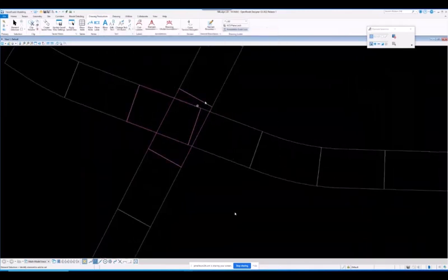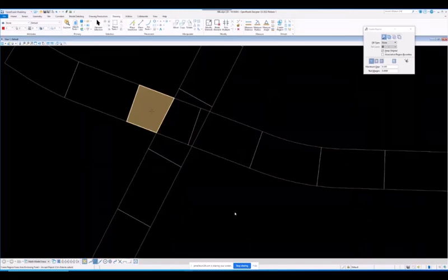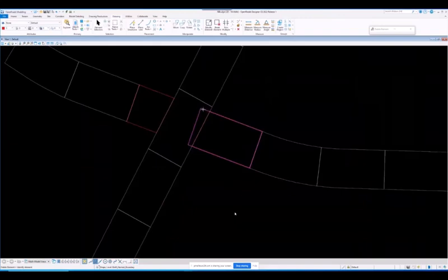In this case, I can't have something clipping the same place 3 times here with the structure. So I'm just going to do some wizardry. I'm going to use the MicroStation flood command. Nobody uses that, right? So I'm going to flood those two name boundaries real quick, get the shapes that I need, and blow the other 2 away. So, okay, I did, but I have some red boxes here that I have to deal with.